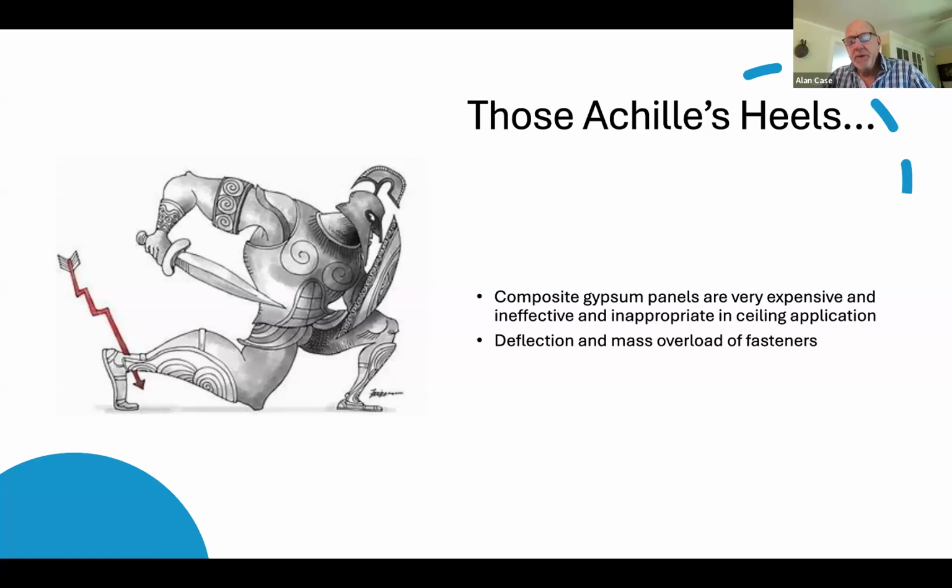Noise travels through in two different ways. You've got structure-borne noise and you've got airborne noise. And airborne noise, when it's in the room, once it hits the surface of the assembly, like your floor, becomes structure-borne and travels through. What it wants to do is come off the back side of that subfloor panel, be it plywood or whatever it is, and resonate, bounce around inside the cavity, and then go to the back of the drywall on the opposite side of the assembly, and then escape into the room.